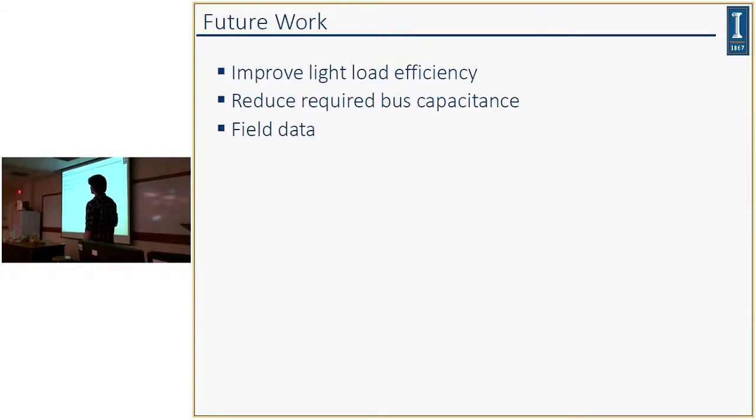And that's an off-board thing too that I need to connect to my PCB. So hopefully I can reduce that by an order of 50. I'm doing that right now at the moment too, and it's looking positive, and I think I can just make it an onboard capacitor, just a bunch of ceramics.